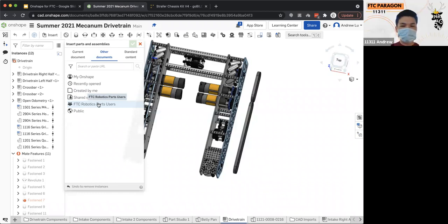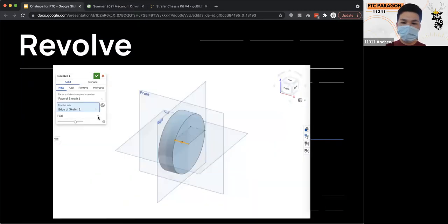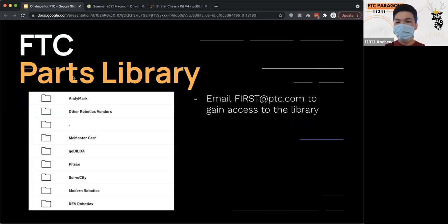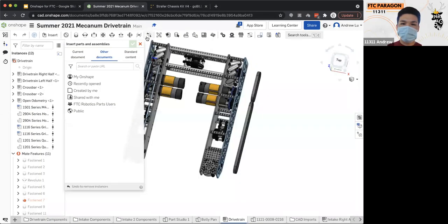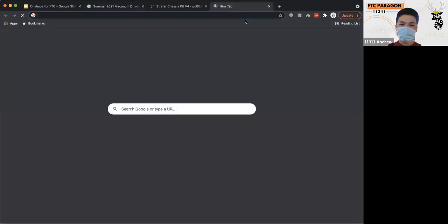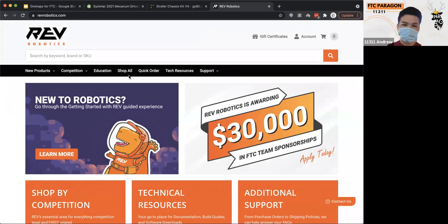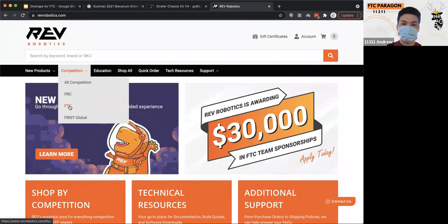Yeah, I think you might need to join the group. So let's refer back to our slides. You need to email first at ptc.com in order to access the parts library. If you want to import parts immediately and it's very urgent, or you're not in the group, you can navigate directly to Rev's website in order to find the part that you're using, and then download the step file, and then you can click the import button in Onshape to import the part. We might just demonstrate that right now.